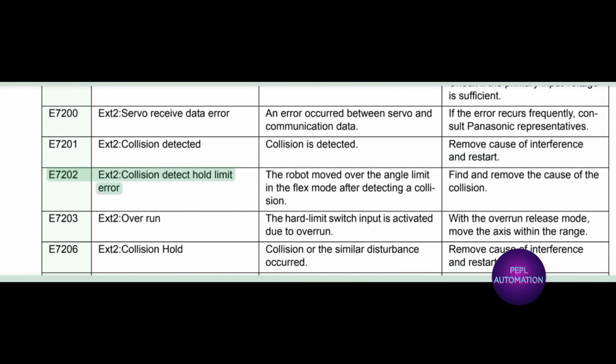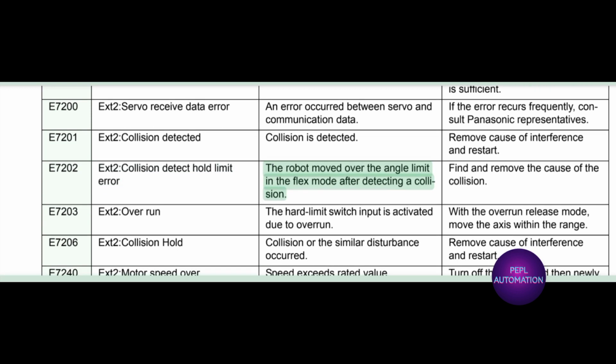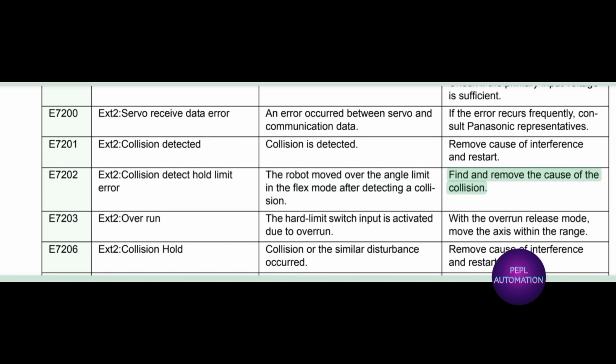E7202X2, collision detect hold limit error. The robot moved over the angle limit in the flex mode after detecting a collision. Find and remove the cause of the collision.